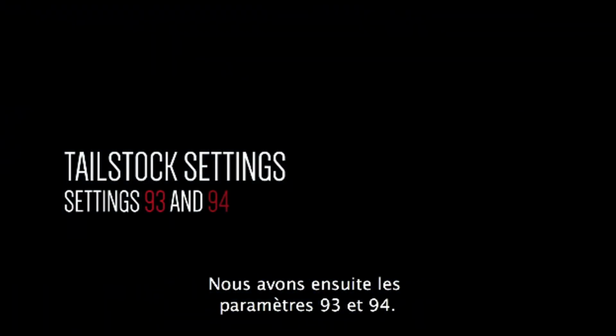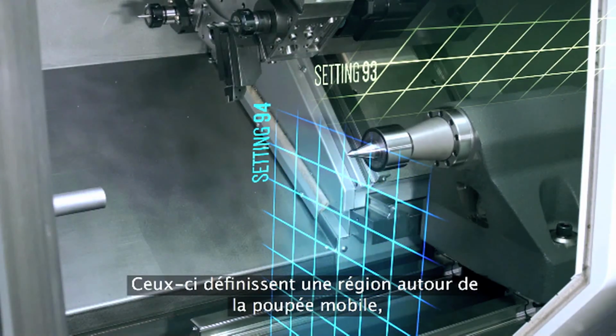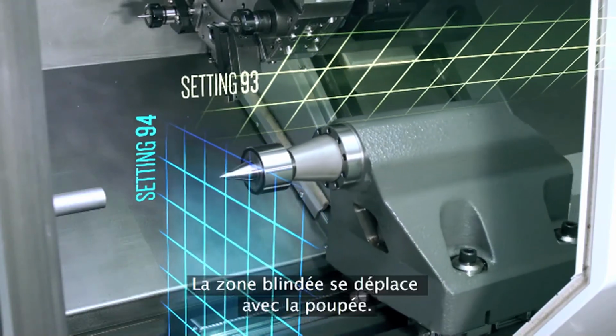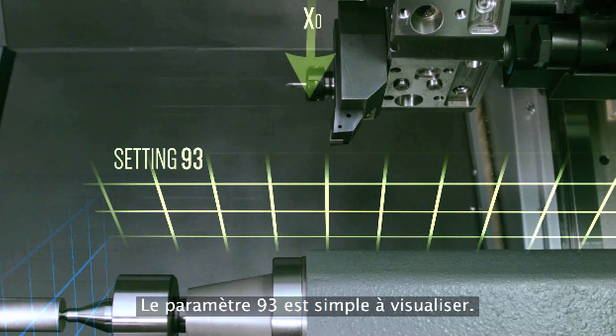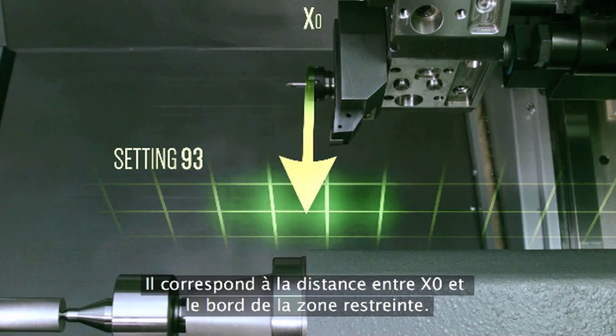Next, we've got settings 93 and 94. These define a region around the tailstock, which acts like an invisible shield. This shielded zone moves with the tailstock. Setting 93 is easy to visualize. It's the distance from X0 down to the edge of the restricted zone.